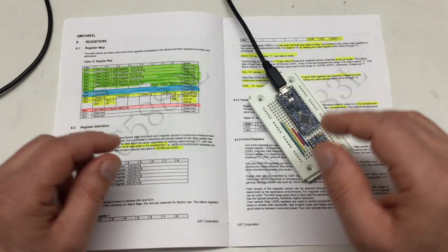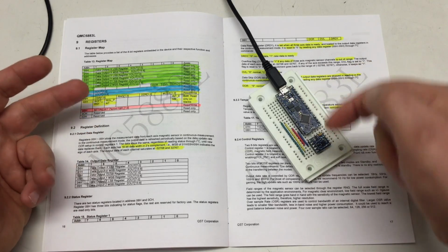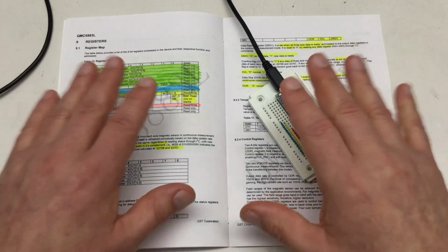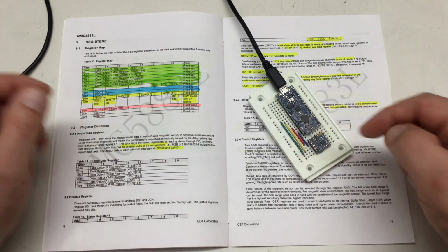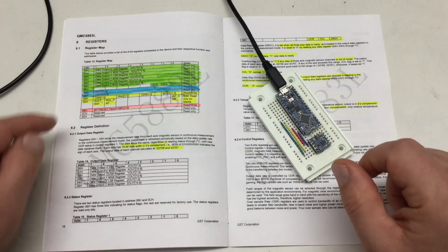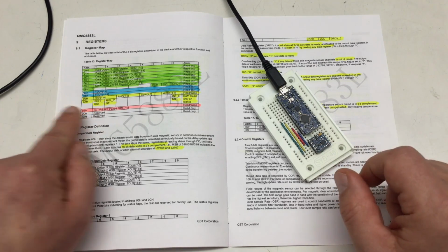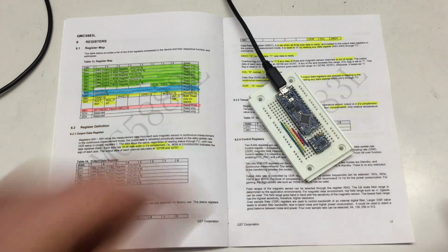We also came up with an architecture for an Arduino library interfacing to that thing, and we took the first steps implementing that library. That is, we wrote the code for the I2C communication as well as reading and writing its control registers. Card here, link in the description.